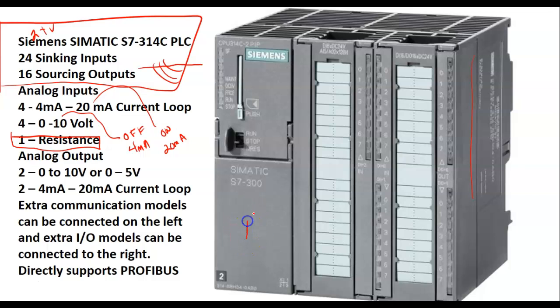It uses what we used to call an RS-232 connection. I'll have to show y'all. Y'all remind me to show the people that are virtual when y'all come in on Tuesday. It's what we call a DB9 connector, and the way it's set up is the female has a metal shell around it. It's up on a plateau, and then the male comes over. It's got a metal shell that fits over the outside, and it's in the shape of a D, so you can't hook this in backwards. We don't like to say things are Murphy proof, but this is about as Murphy proof as you can get without cutting the shell off.